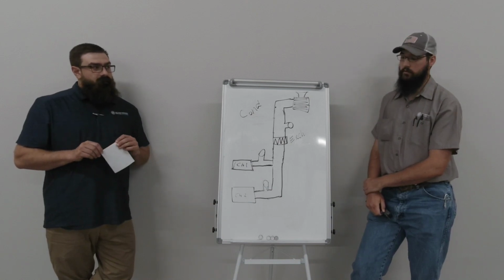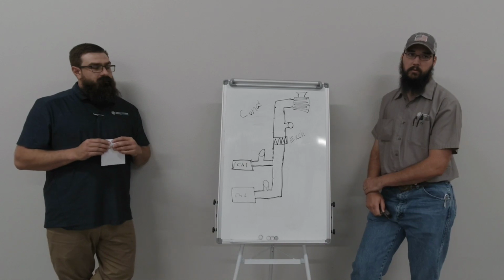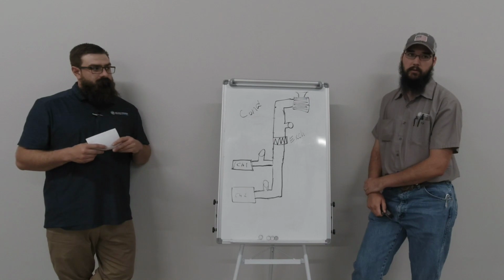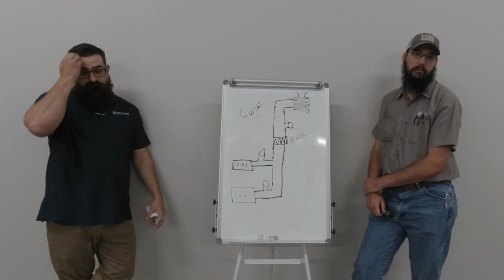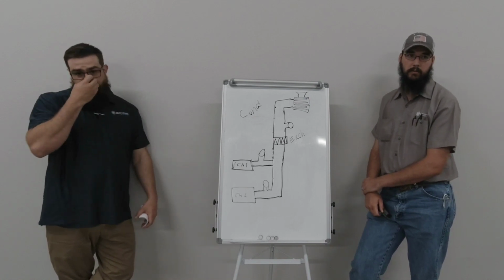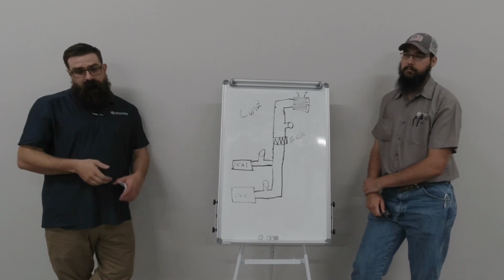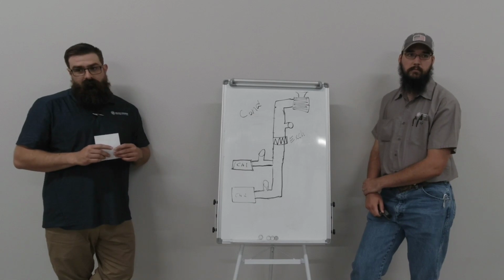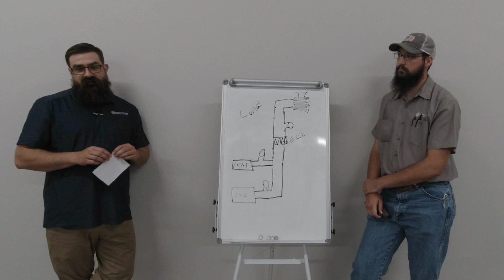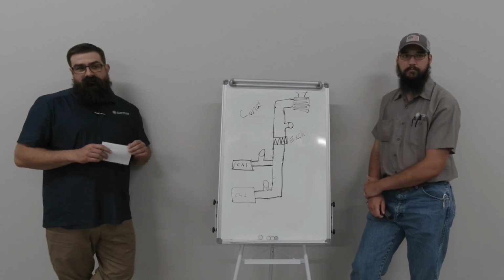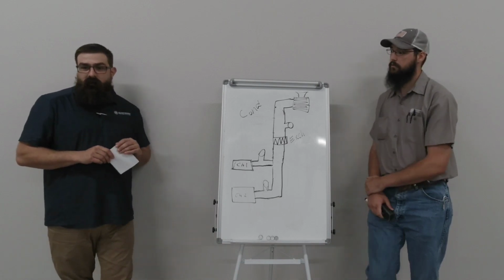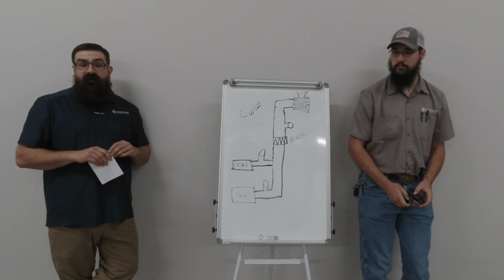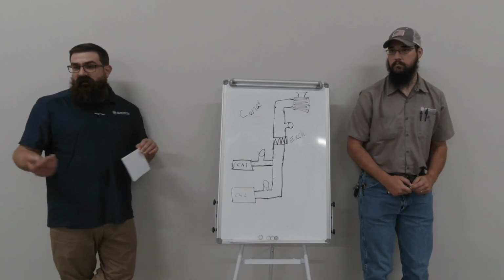Because the tolerances on those compared to a normal barrel exchanger are night and day. I mean, very slim tolerances versus a barrel, where you could dang near have a tube plugged up and still get some kind of heat out of it. Those plated ones, I mean, they're not easy to clean. You check differential pressure loss across it, temperature variance. So entering and leaving pressure, if your entering pressure is much higher than your leaving pressure, it's clogged.